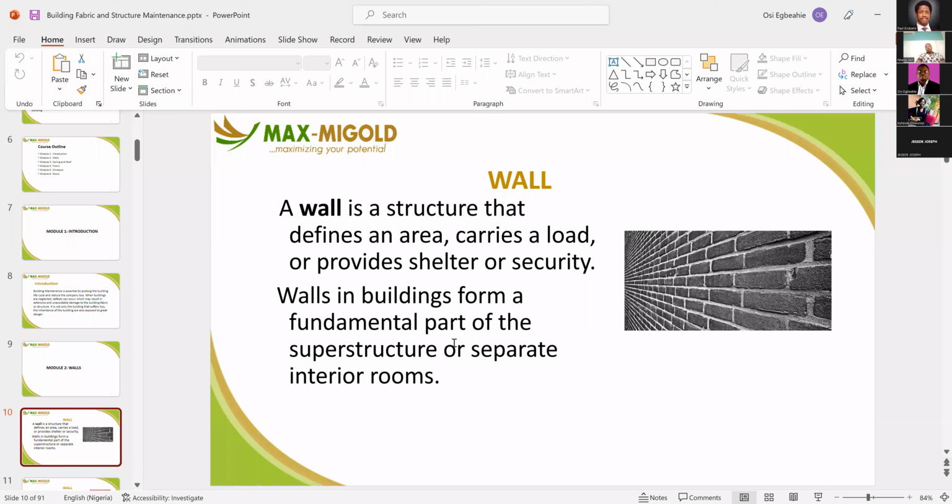And when you go to warehouses, the underneath of those steel stanchions that you see is normally carried by the pad foundation. You also have the pile foundation, which is traditionally used for high-rise buildings, for skyscrapers, and for the construction of bridges, and where the load-bearing capacity of the soil is extremely bad, and you need to get contact to a more stable soil, which is usually far down into the earth crust. That's for foundation.